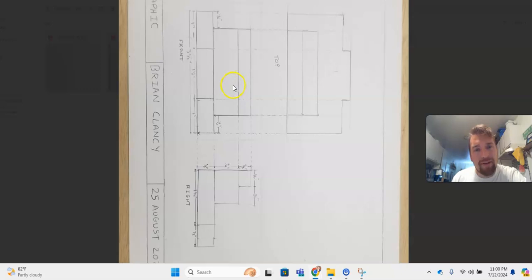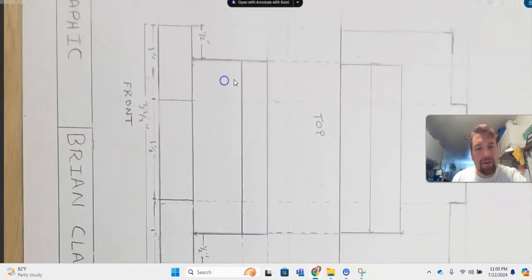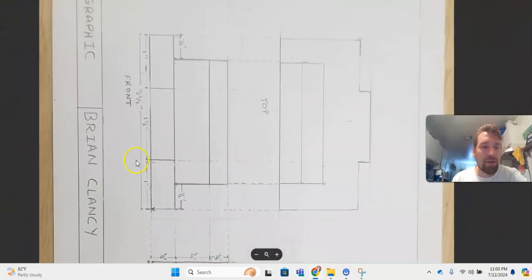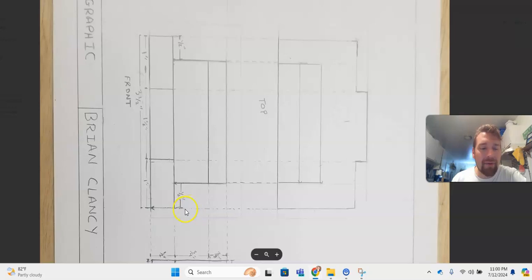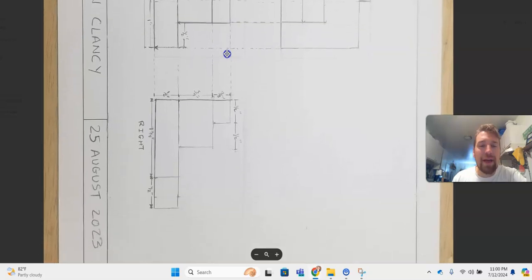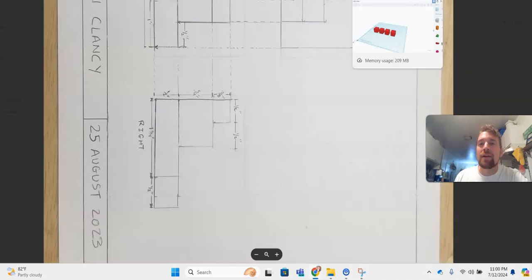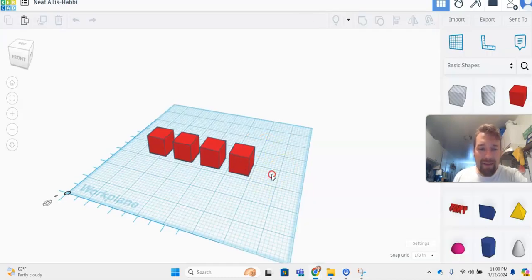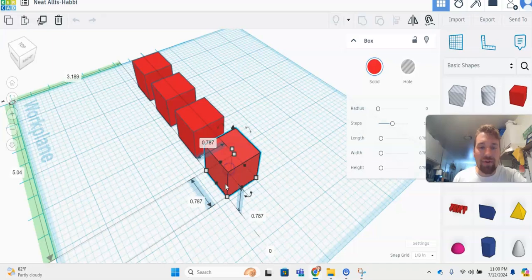to get my width right here. So it's looking to me like the width of the top box, we know that this entire width right here is 3.5, and then we're going to subtract 1/2 for this edge and 1/2 for this edge. So you're subtracting an inch from 3.5, so we know that this is 2.5 right here. So we know that the dimensions of our block are going to be 3/8 high, half an inch wide, and then in depth it's 2.5. So again, using the same methods that we've already learned how to use, again, pretty straightforward here.